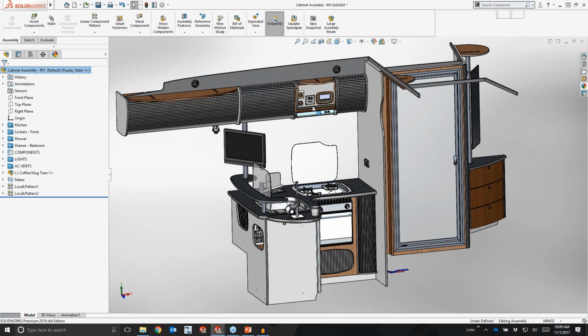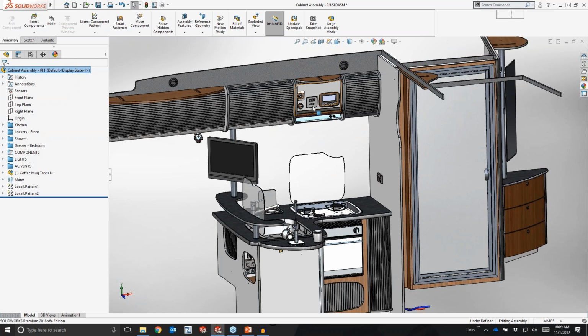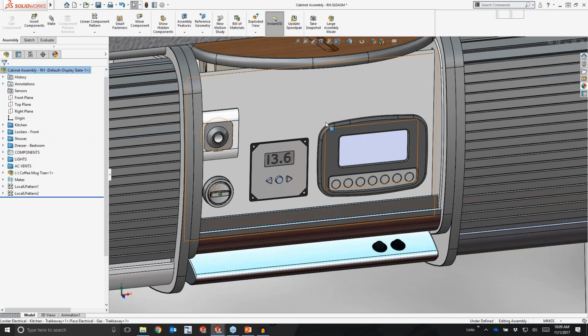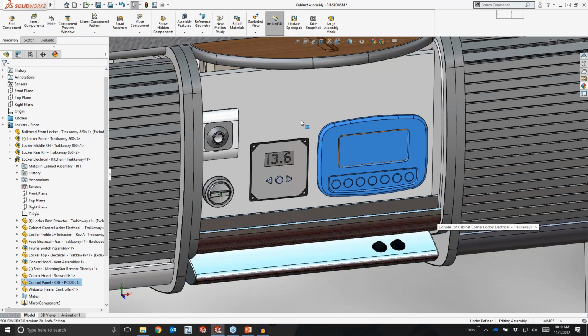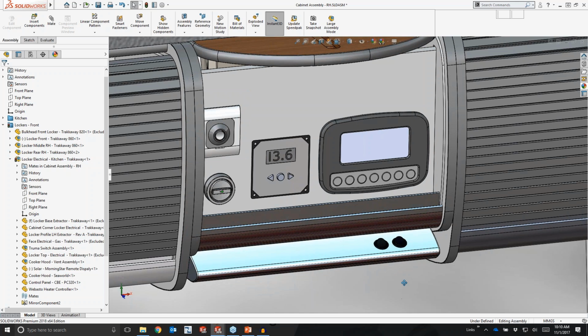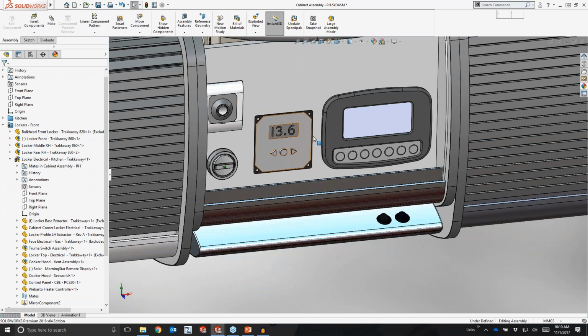I need to grab a couple components here on this panel. And to grab it and make sure I grab the whole thing, I'd like to box select. But when you box select over a panel, it doesn't allow you to do the box select. It tries to drag your panel. So SOLIDWORKS has added a new keyboard shortcut, the T key. When you hit the T key, it allows you to box select over geometry. And if you do Control T, you can then select multiple things or continue selecting things very quick and easy. So the T key is going to be a big help for anyone trying to make box select of a small component in the context of a much larger assembly.